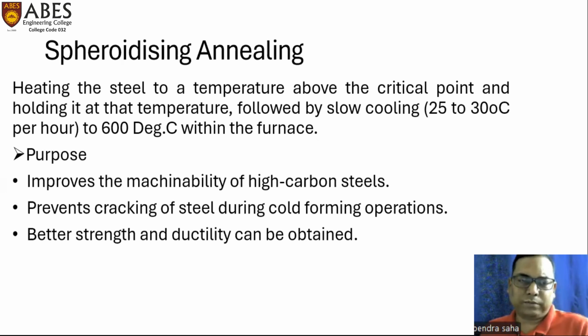The structure of the carbon or grains is needle like. So obviously when any machine tool impinges on this material, a crack may propagate or very improper machinability happens. To remove such obstruction in the material, the spheroidizing process is applied.